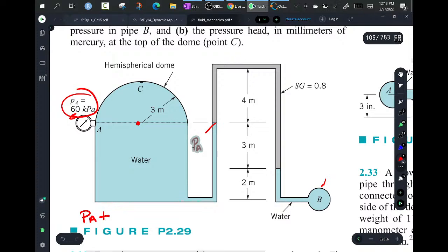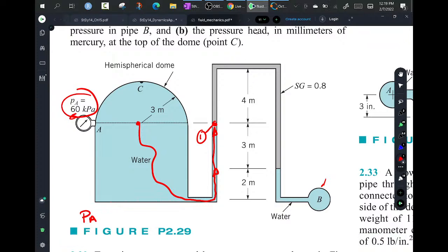Now you could write a spot 0 there and say PA plus nothing is equal to P1, or you could just recognize that and say, hey, I went down, and every time I go left or right, there's no change of pressure, but when I go up or down, there is. Went to here. The next thing I do is they go through this little bit lighter fluid than water, like an oil or something. So if you pour oil inside water, the oil kind of floats on the top. And that can be problematic.